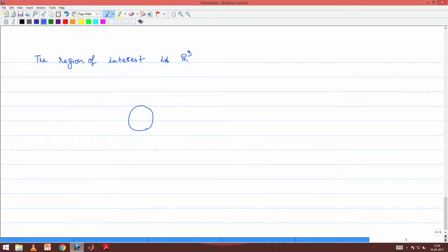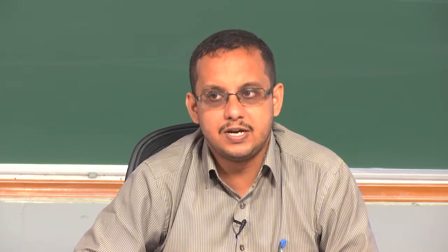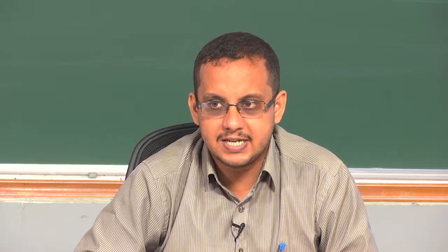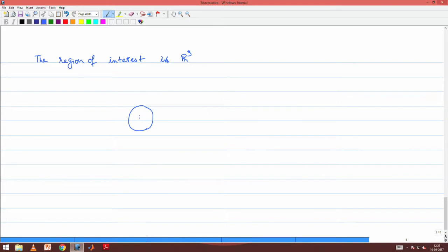The way we approached the solution of the monopole or pulsating sphere was to consider what happens exterior to the sphere, right. We were trying to match the vibration velocities exterior to the sphere and thereby we got the outgoing wave solution. But now we are saying that instead of trying to match the exterior to the sphere, we will keep the sphere included within our domain of interest, but we will just say that at this point there is an imbalance of mass or volume, whichever you may call it, right. There is an imbalance in mass and this imbalance in mass will have to be rightly accommodated. If that can be accommodated, we will get the inhomogeneous wave equation. So, let us turn to that argument.